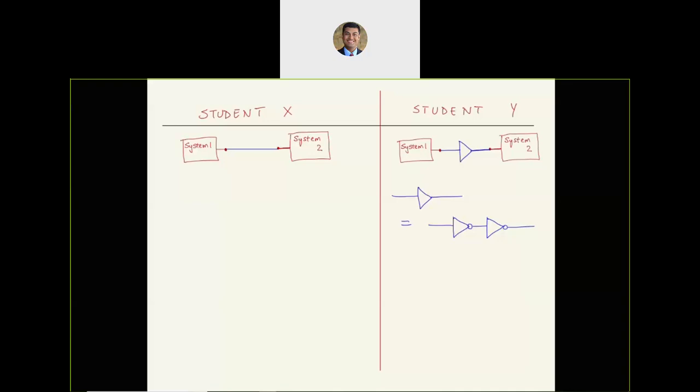Well, who is going to be right? Are they both going to be right or not? They are both going to be right only under ideal conditions, meaning that we have a very strong output over here. And we talked about what a strong 0 or a strong 1 means. If it is a strong 0, it's 0 volts, or 5 volts in the case of high. In that case, the translation of the output to the input here is going to work out okay.